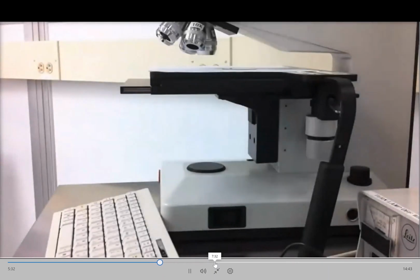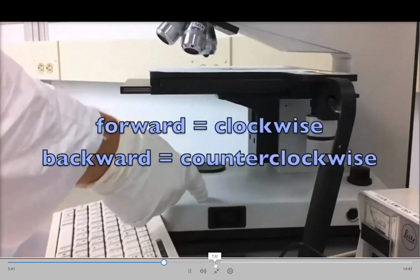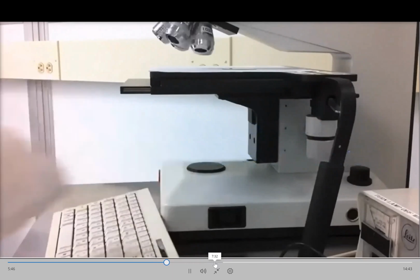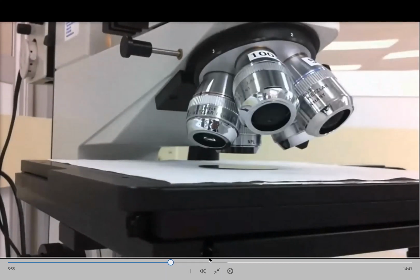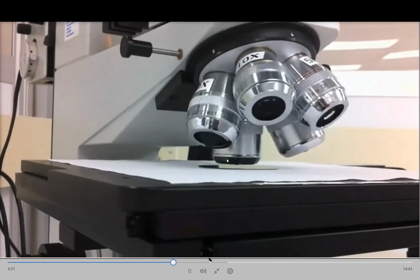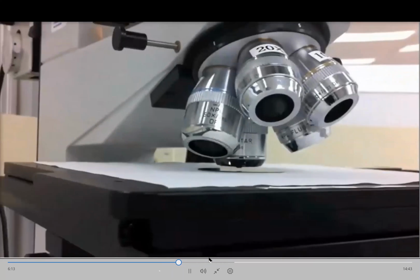On the bottom right side of the tool, this two-way switch allows us to rotate through the various objective lenses. Pushing forward once rotates clockwise to the next objective lens, while pushing backward rotates counterclockwise. Whenever loading or removing a sample, be sure that you have the lowest magnifying power lens in the bottom position. This gives you more space between the lens and sample, because weaker lenses protrude much less than higher powered lenses. Also, the 50 and 100x lenses are much more expensive. So always begin at the lowest magnification, focus, and then proceed to higher magnifications.